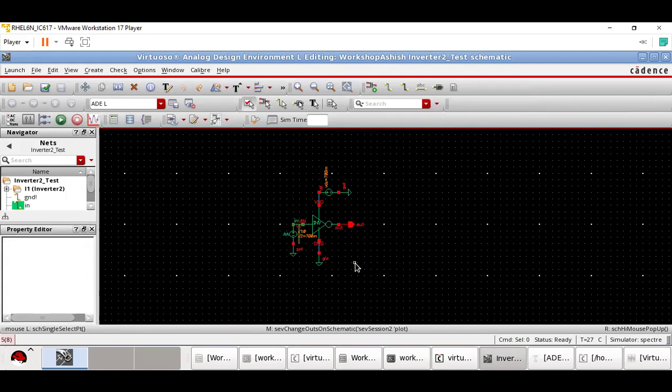Now, if I ask you to create a circuit with a fan out of 4, do any of you know about the circuit of fan out of 4? What is the meaning of fan out in digital? Anyone? Sir, I think the number of outputs it can drive. Yes, the number of gates that can be driven by the similar gate. For example, if I'm having the AND gate here, how many AND gates it can drive from its output? It is the fan out.